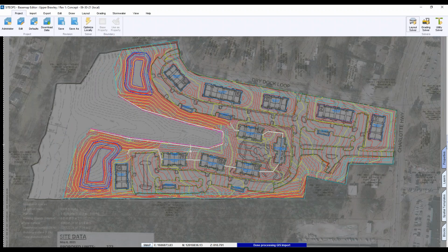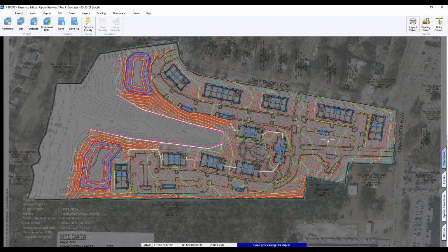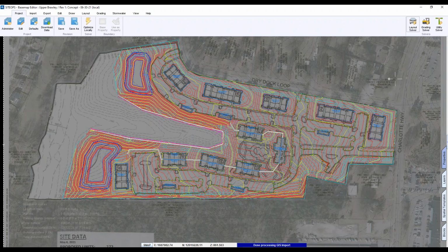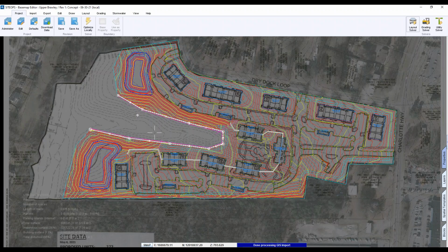So we build both. We build the urban and the suburban. And so the suburban, we get ones that look just like this almost every time. A guy hand sketches an overlay over something, and we run, the first steps are exactly the same. Pick 2 common points, find it in ESRI Geolocate, find 2 common points there, draw a line between the 2, get them lined up on Earth, and then go to town.